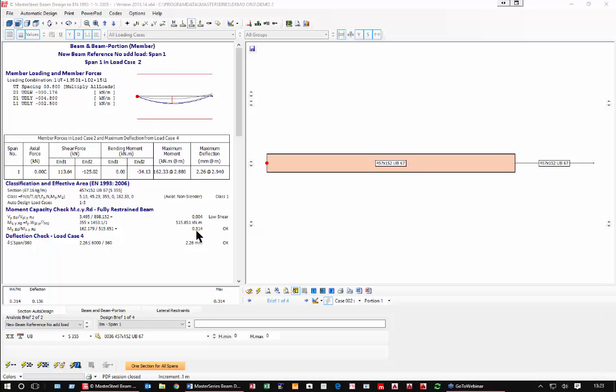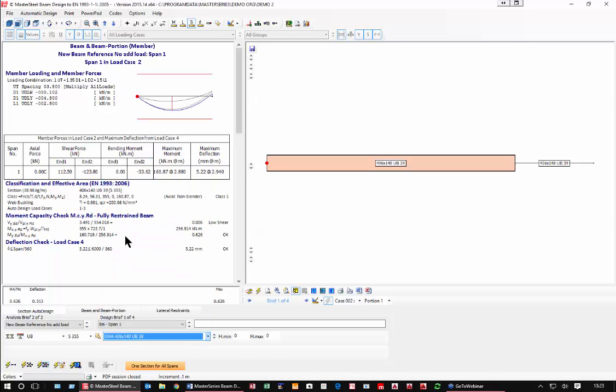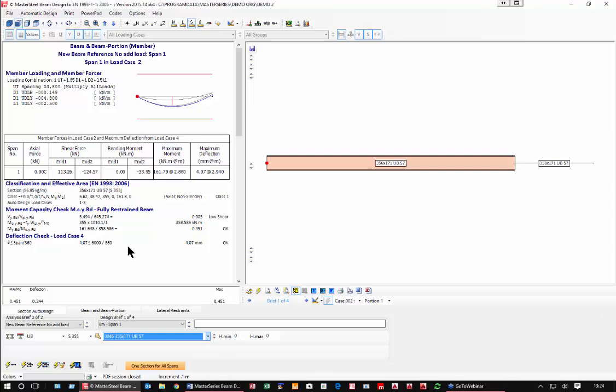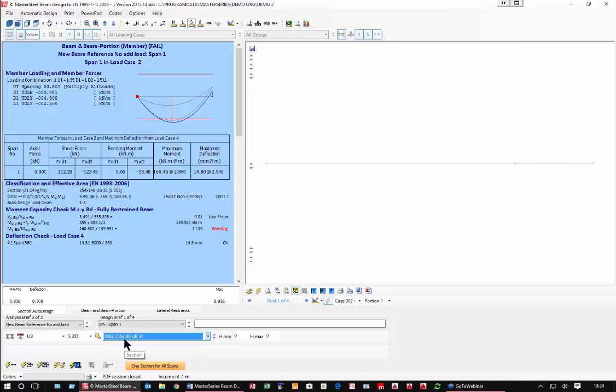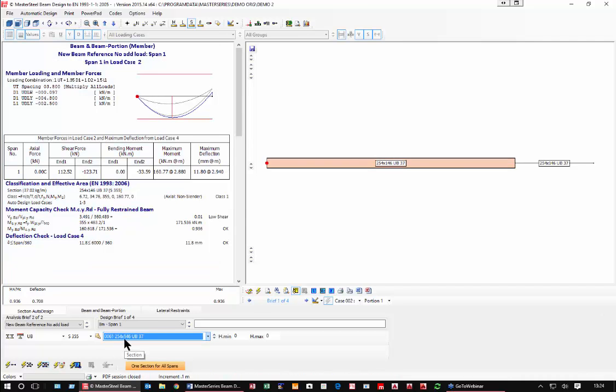So if we're not happy, if we've not got a problem with deflections, we could reduce this beam size right down. So if we work with these deflections that we've got here, we can come along and say, take this beam and come down to 406, 356, coming down again, just down through the list, 254. So the shallowest section that's going to work is the 254 by 37.